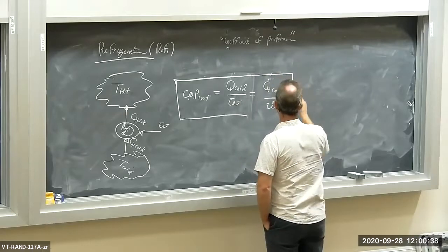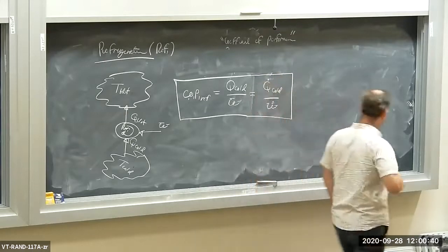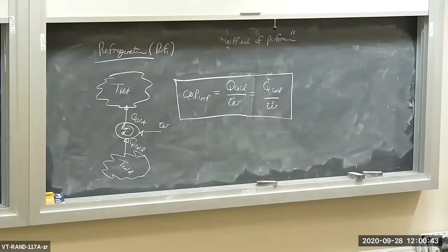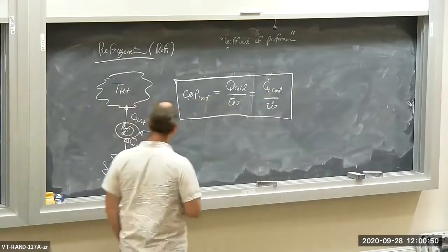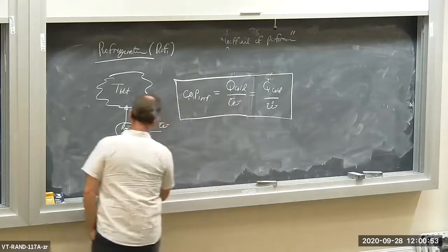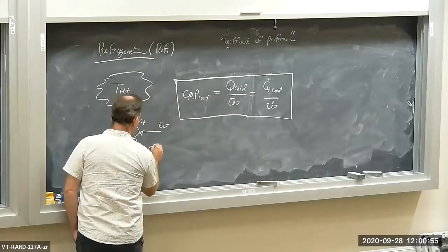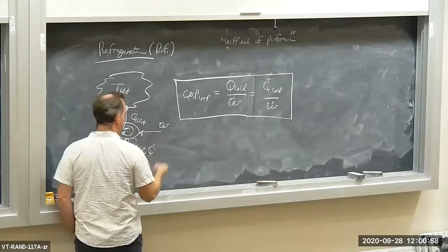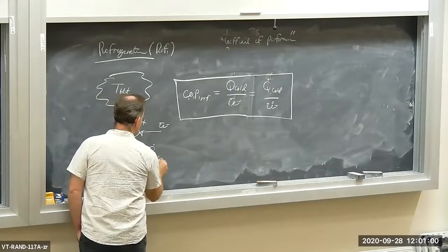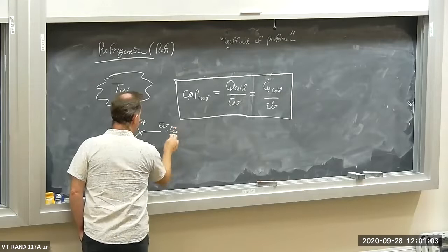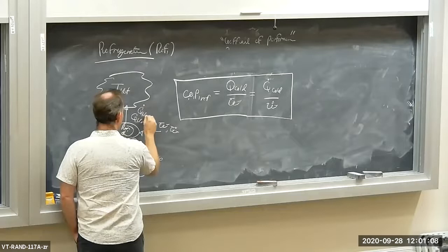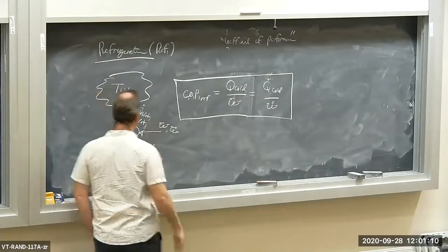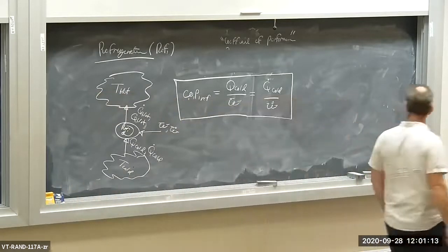Change in any property is 0 over time. For the continuously running device, Q dot cold over W dot, or Q cold over W. Okay? So let's extend the picture here. I can also write this. If it's a continuously running device, I can write this as Q dot cold, W dot, or Q dot hot. Okay? It's for a continuously running device.